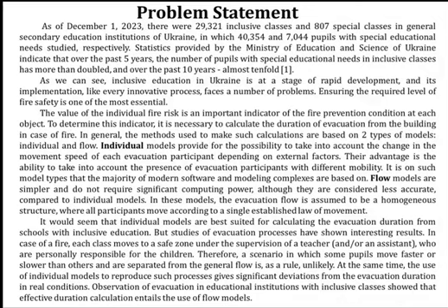There are two groups of models that we can use for that. The first group is individual models. They provide the possibility to take into account the change in the movement speed of each evacuation participant. And the other group is flow models. The evacuation flow is assumed to be a homogeneous structure where all participants move according to a single established law